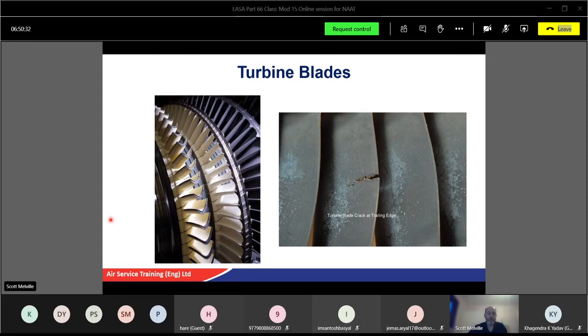Erosion is normal, up to the point where the wear and thinning off will distort the airflow as well. You will get deposits sometimes, so again, check the colour of the deposits. We've had occasions where aircraft were flying through volcanic ash, with Iceland back in, I think it was 2009, 2010. The volcano erupted in Iceland, and the cloud of smoke was coming towards Scotland, and we had to check the aircraft every flight for potential ash ingestion, because the ash would melt and block the cooling holes, etc. And we did find some, to a point where we rejected some engines. So take your time checking them.